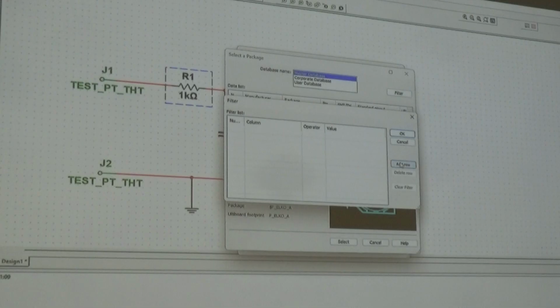Now inside here you've got where you can edit a filter. In other words, you can write your own filter. And what I want to do here is click on add row, and filter according to whether the package has got the word res in it. Might be resistor, might be 123 resistor, might be 123 res 1000, but it's that magic RES that I'm looking for.